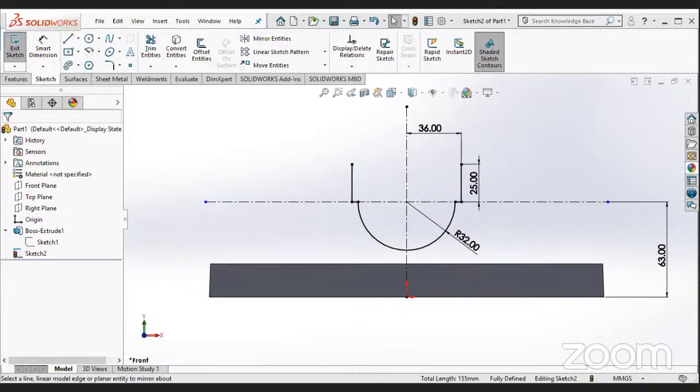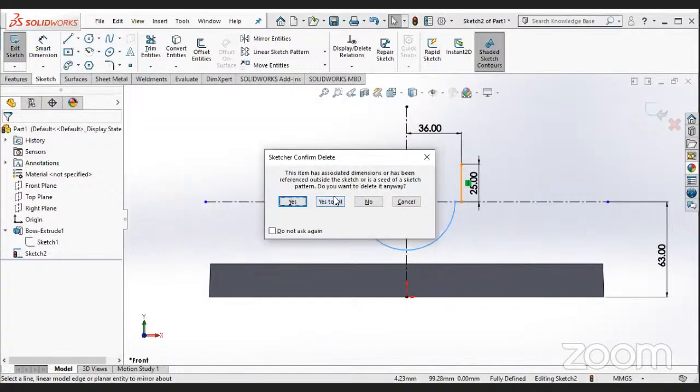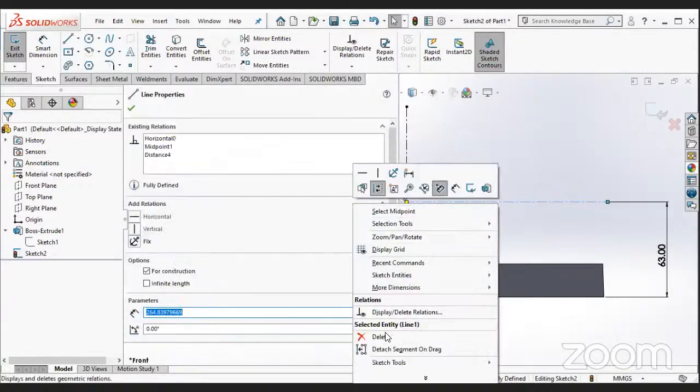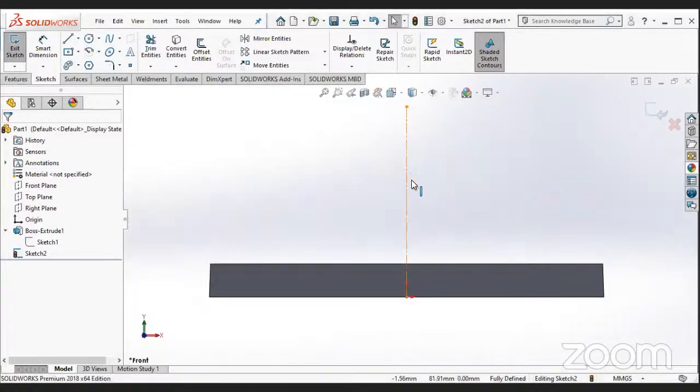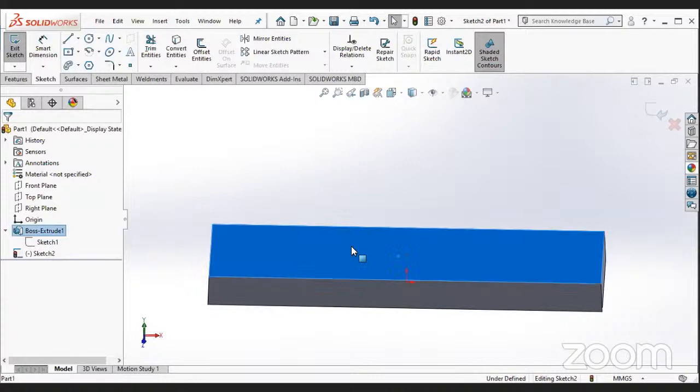So when you have here 64, it means the length of the base. So what we'll do, if we have a dimension of an arc, which we don't have here, we'll assume that dimension of the arc is 64, and we'll try to make a block first and then we'll extrude cut this part. Let's start with this. I'll just quickly delete this. And we'll start making the block from down. So I'll sketch on this surface.